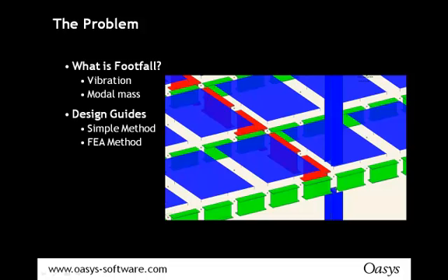You also need to look at restraints in the structure. Footfall is unusual because normally the perimeter structure supports the cladding, but under footfall vibration it's the other way round. The cladding supports the structure. Likewise, pin connections in steelwork are modelled as fully continuous because the strains are so small with the vibration that the joints are not actually mobilised.